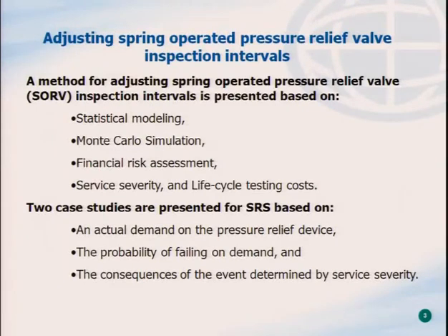New valves are valves that we've purchased from manufacturers, and also valves that we have rebuilt and placed within service within a few months. And the testing, basically 4 tests are conducted. The first test is the as-found condition, and 3 subsequent tests are averaged to get us the average of the last 3. But the one of primary importance is the first pop pressure.